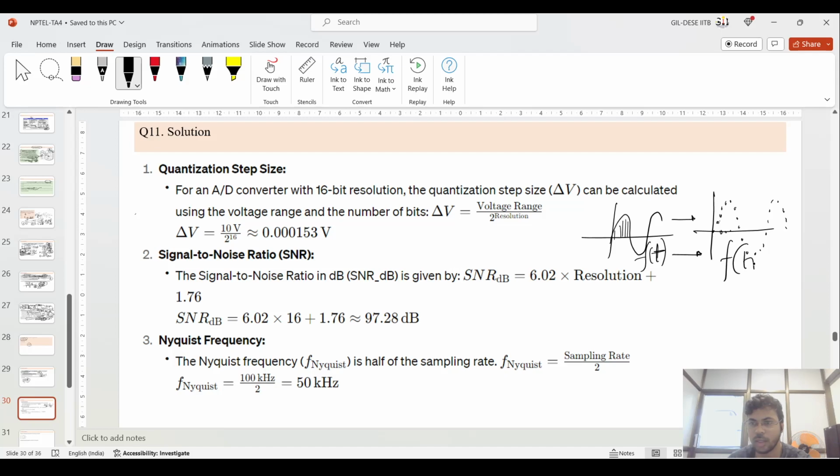If it is a time domain signal f(t), then you convert it into the discrete domain by setting t equal to n Ts, where n is the number of that instant, say 1, 2, 3, and Ts is the sampling period, so Ts, 2Ts, 3Ts.